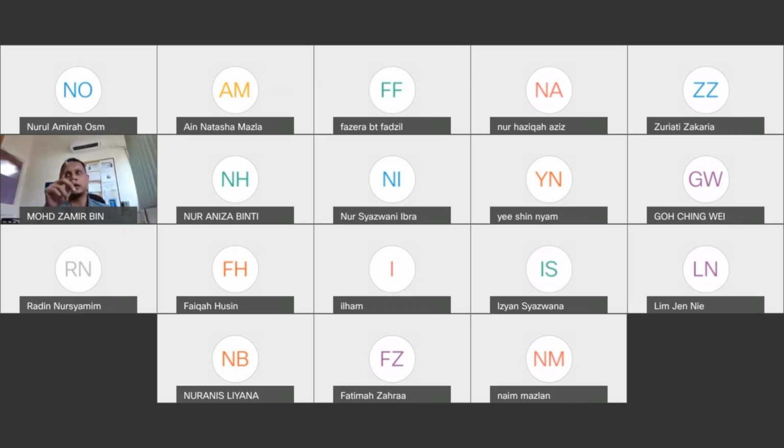So if you look at wafers with those kinds of surfaces, either double sided or single side, you will be able to detect the difference, right? Usually, either you go for single side polishing or double side polishing. It depends on what sort of application. For my case, it's one side polish. That means I use this one for solar cells because I only need one side. I don't need both sides to be polished.